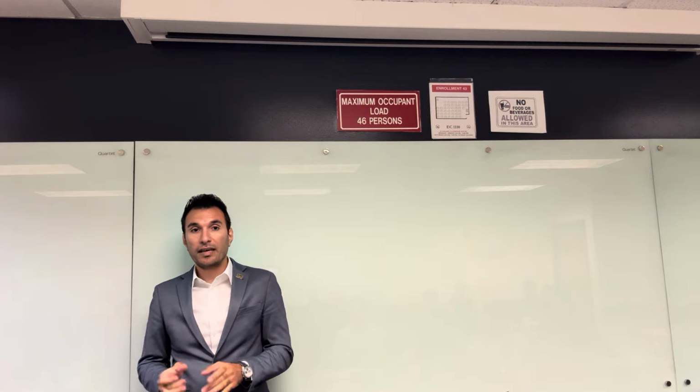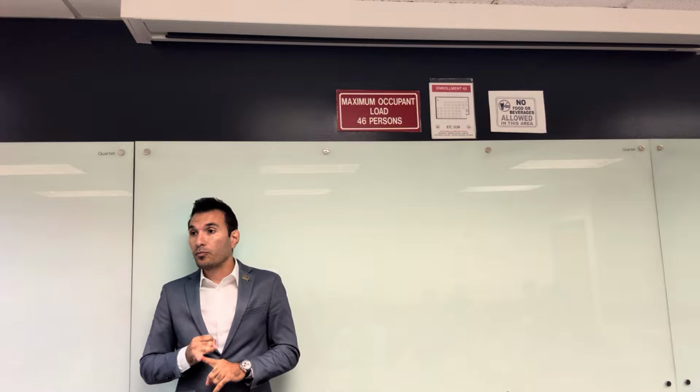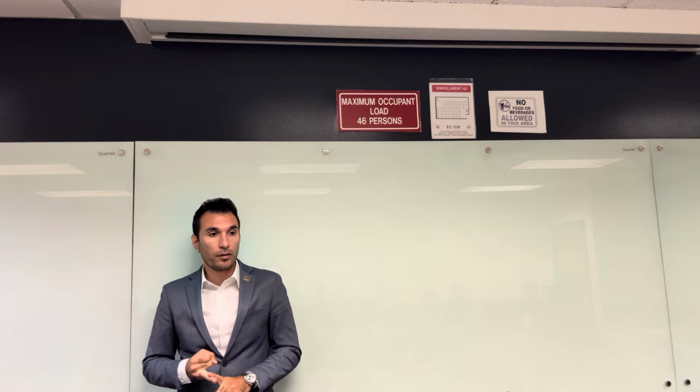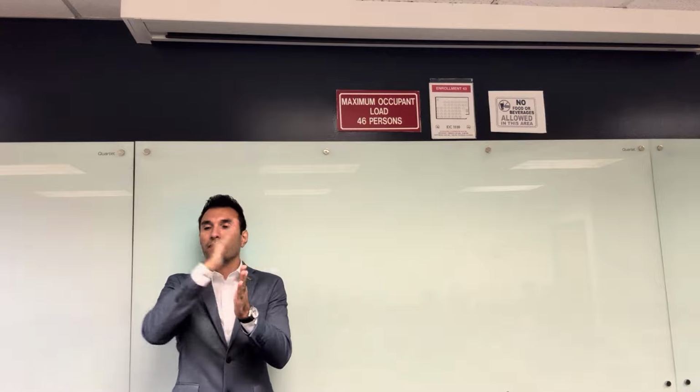So what is your method? And then in the methodology, for any tall building design project or analysis project, I need to see a full profile of the whole building. Don't miss that, either in the presentation or in the final report. I need to see how the building looks. And also the deformation. I want to see the deformation on the whole building, the drift, the total displacement. So I need to see all that.